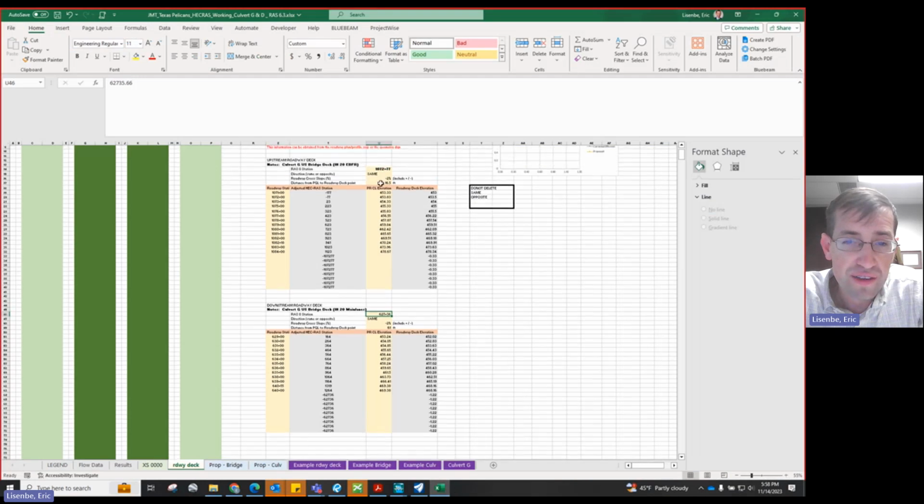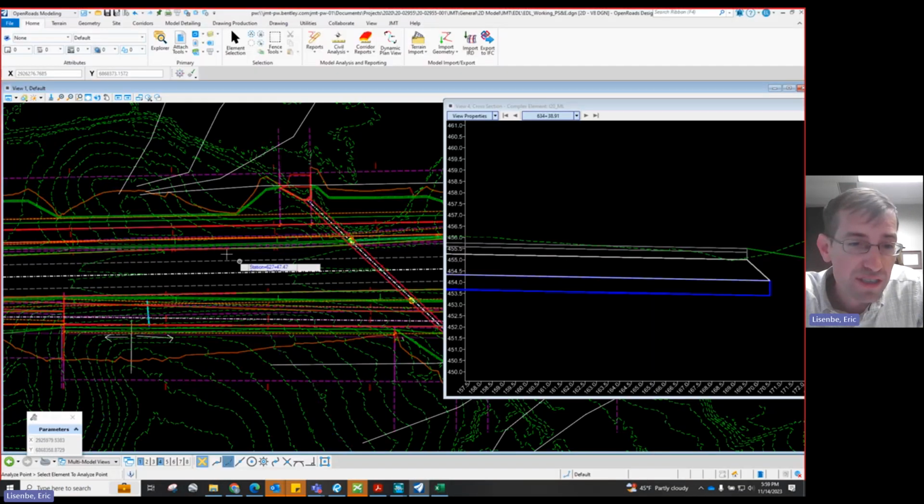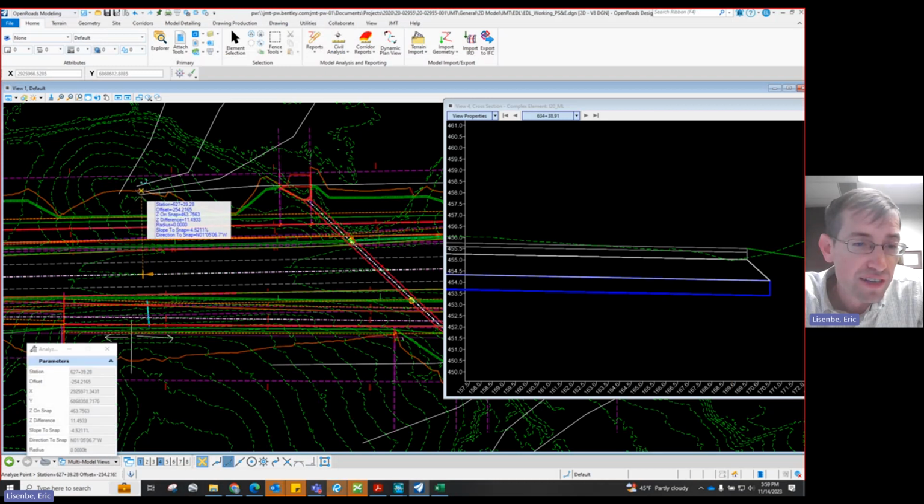We've fed a little drop down into the equation, and you just select opposite if it's going the opposite way, and it adjusts these equations for the stationing to do a little bit of algebra and figure out what it'll be when you're going backwards against the roadway stationing. So this one we had 627.36 for the 0, and that's by clicking on this and then going here.